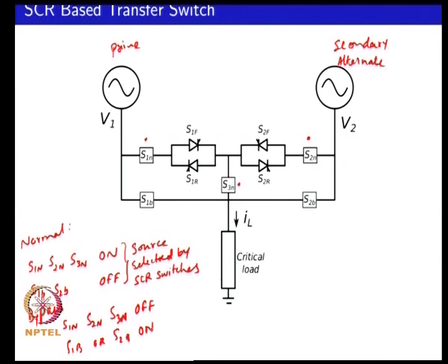So, you might make use of these bypass switches to say, for example, if you want to repair your main SCRs and still provide power to your critical load, or you want to do some modifications on your alternate source, you might typically operate it in a bypass mode and then ensure that whatever servicing, repairs, etc.